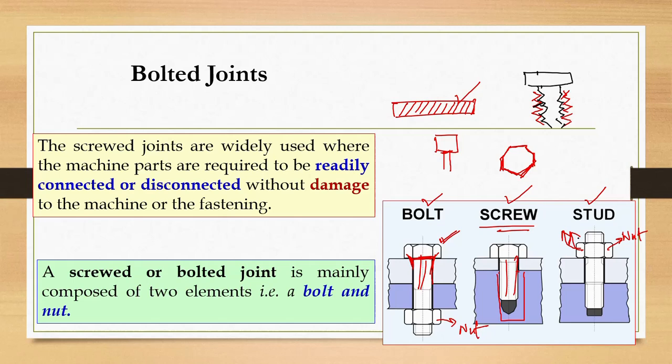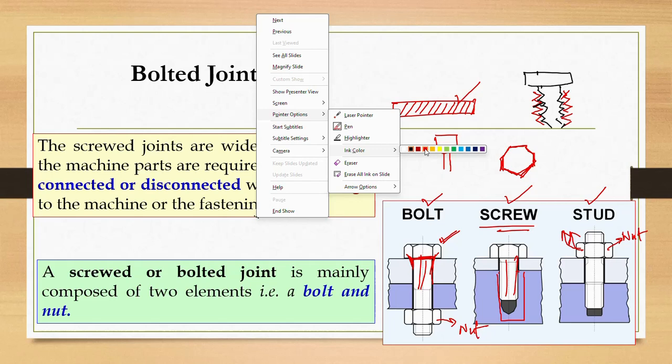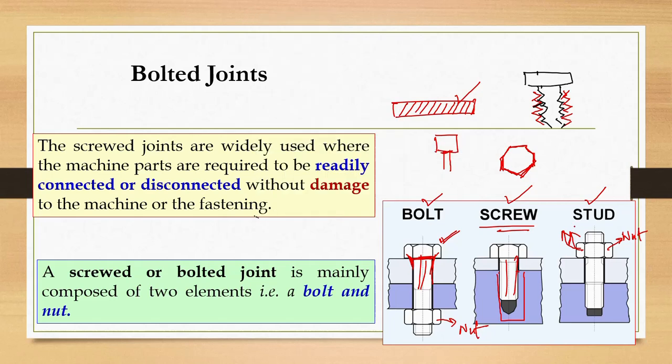So in the case of studs, the stress is borne only by the threads, not the head. That's why studs are not as good in bearing those stresses as compared to a bolt. But yes, as I mentioned earlier, they are customized. You can use them in very large lengths, like in feet, whereas bolts are generally available in standard sizes.